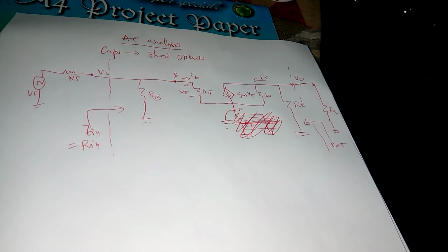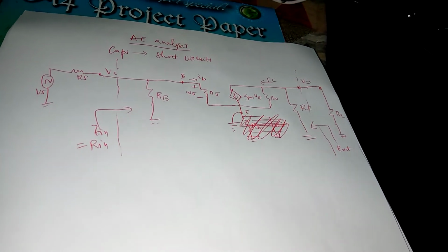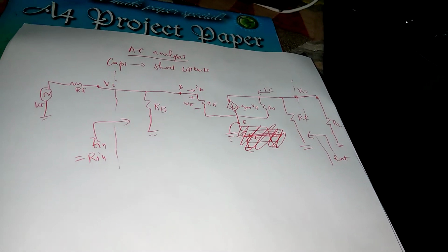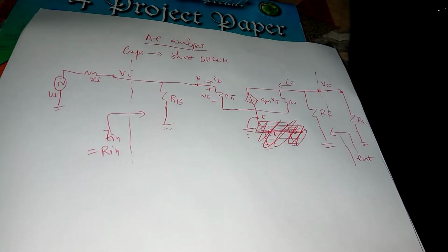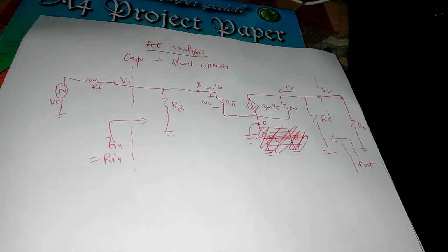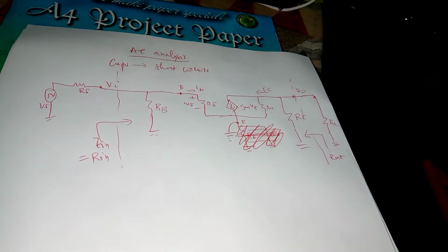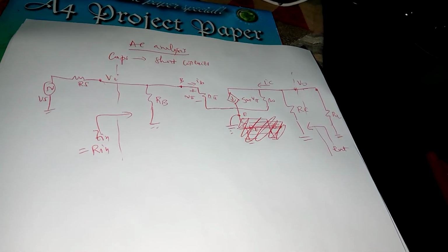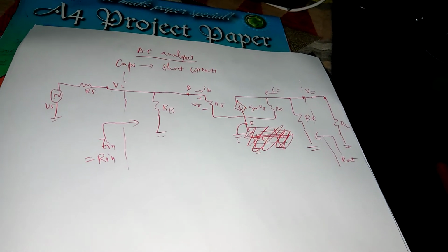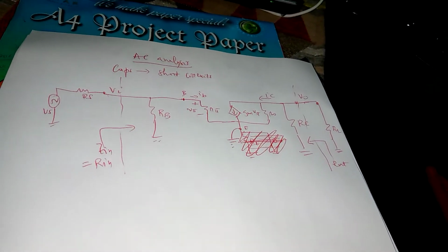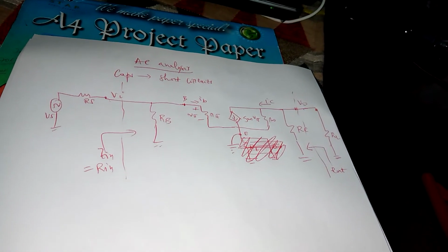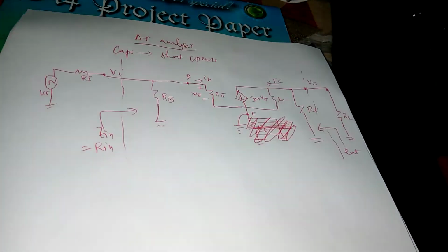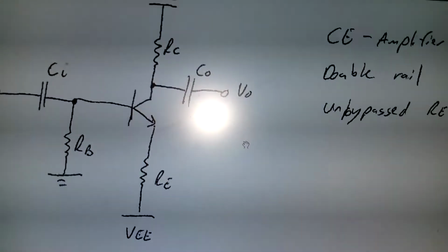So we can also have the common emitter double rail, but which is unbypassed. And that's the note on page 5. The common emitter amplifier notes take you through that. Highly encourage you to analyze it and derive the formulas as well. It's going to be very similar. The DC analysis is what changes a bit. Actually, it's going to be the same as what we just did now. But in the AC analysis now, since there's no bypass capacitor anymore, we'll just have RE. RE will be present now on the emitter, and we know the implications of that. Okay, very good.